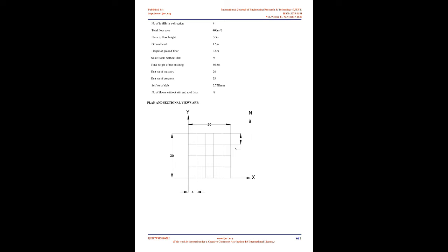The earthquake causes vibratory ground motions at the base of the structure, and the structure actively responds to these motions. For a structure responding to a moving base, there is an equivalent system. The base is fixed and the structure is acted upon by forces, called inertia forces, that cause the same distortions that occur in the moving base system. In design it is customary to assume the structure as a fixed base system acted upon by inertia forces.